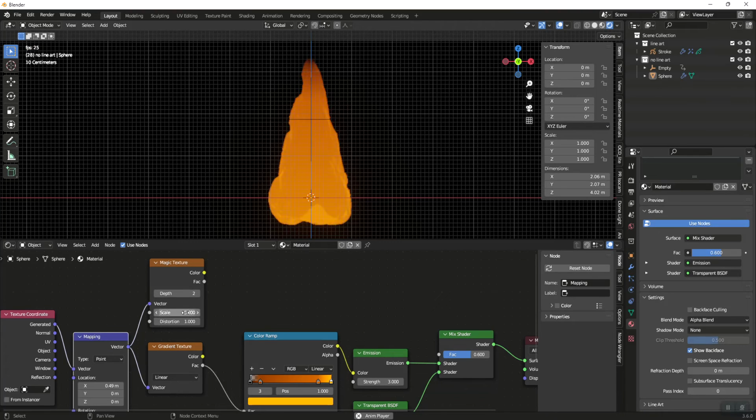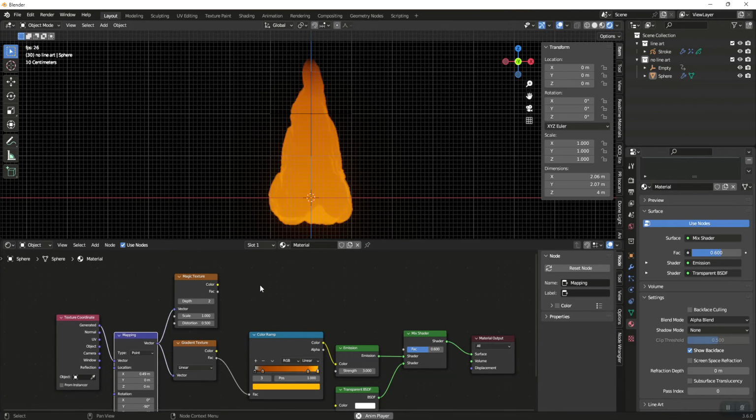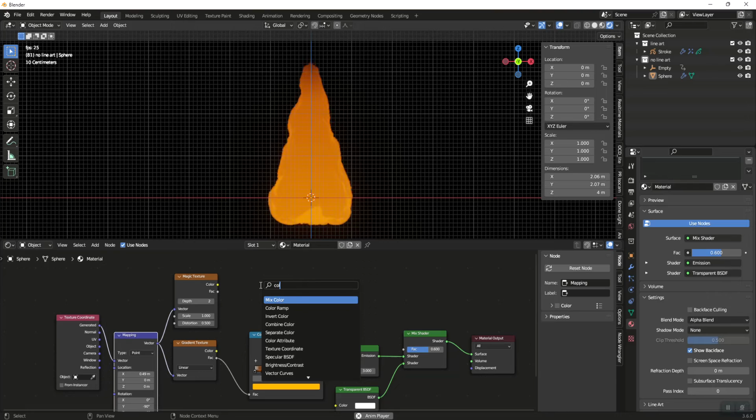We're going to leave the depth at 2. We're going to drop the scale to 1. And then distortion, I have played with everything from 0.5 to 5. And it's just going to be a matter of what works best for you guys. That's going to be one of the sliders I recommend we play with to get the ripples exactly the way we want.